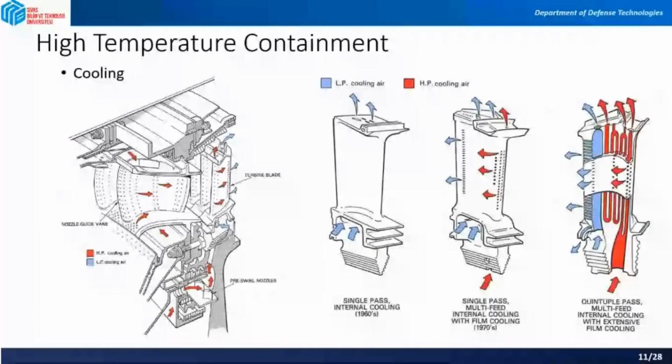And if you notice, there is a pressure nozzle in the left figure at the bottom. This reduces the temperature and pressure of the cooling air fed to the disk for blade cooling, and the nozzles also impart a substantial swirl velocity to assist efficient entry of the air into the rotating cooling passage.